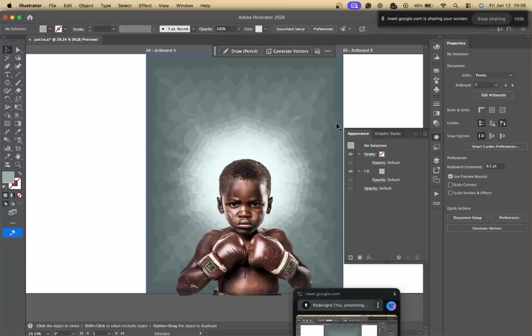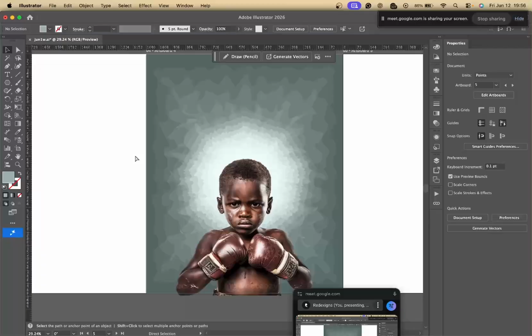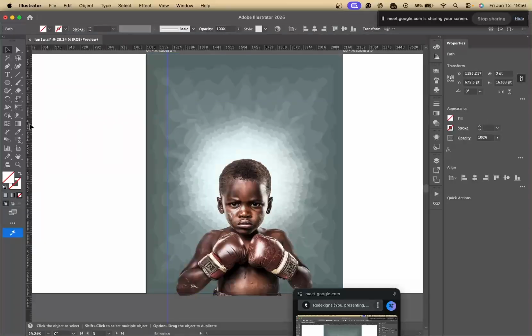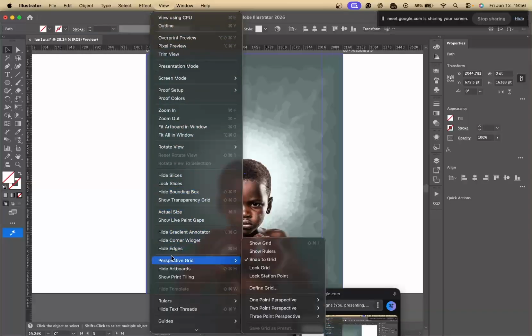So with practice you begin to observe, or you have an imaginary line that is on your screen. But in case you don't have an imaginary line, you begin to introduce what they call a ruler. Now, if you press Control R on your system or Command R, you could drag a line to position in your frame. You could drag another line to position in your frame. Now, if you check, my snap is on, so there's something called snap, it's actually under the view here, so it snaps to grid.